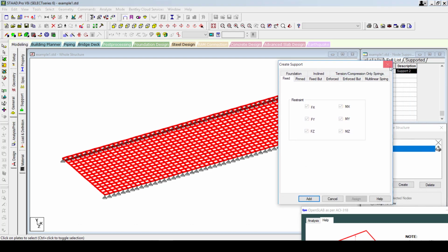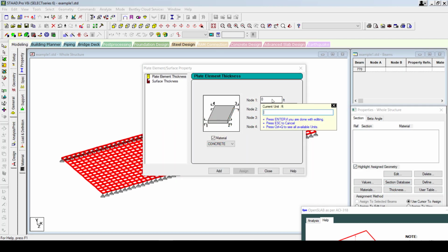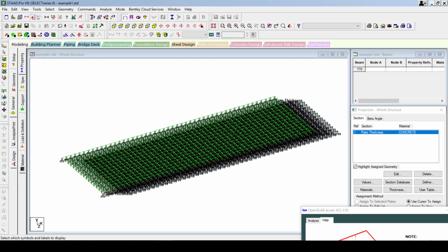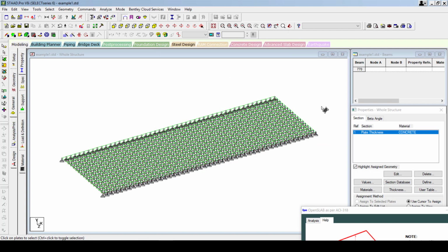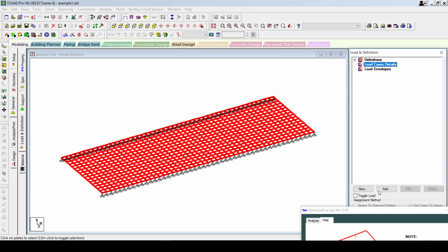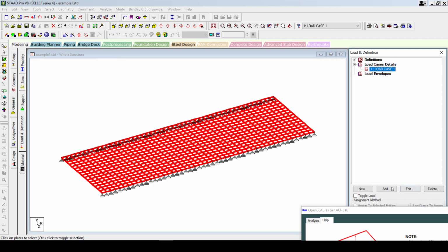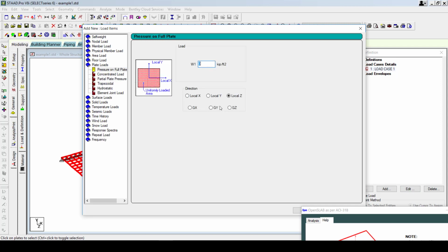Sorry, I'm going to assign the property thickness. So 7, I'll use unit converter, 7 inches. There I go, in feet. And that's that. Now the only thing left to do is assigning loads to the whole slab. Let's assign load to this plate. If you want to create load cases and then combinations in STAAD, that's your thing. But right now, for the example's sake, I'll just go ahead and create a simple load case and apply a load to the slab, plate load, and GY direction.